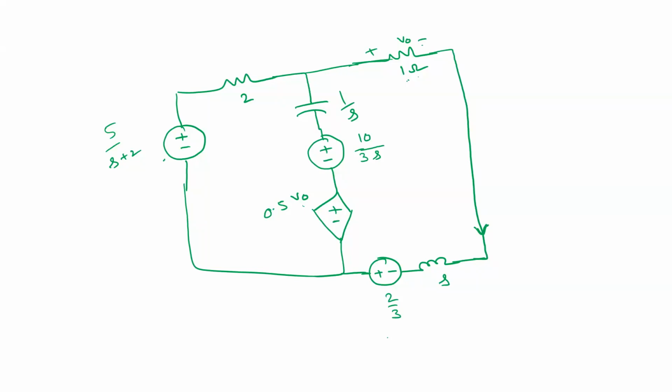Okay, fine. So here the thing we need to remember is, if you have a dependent source, there is no change in that. It is already depending on that V naught. Whenever you take the Laplace of this one, automatically you consider it here. Understood? So now it will become V naught of S. So this also becomes V naught of S. That's the thing.